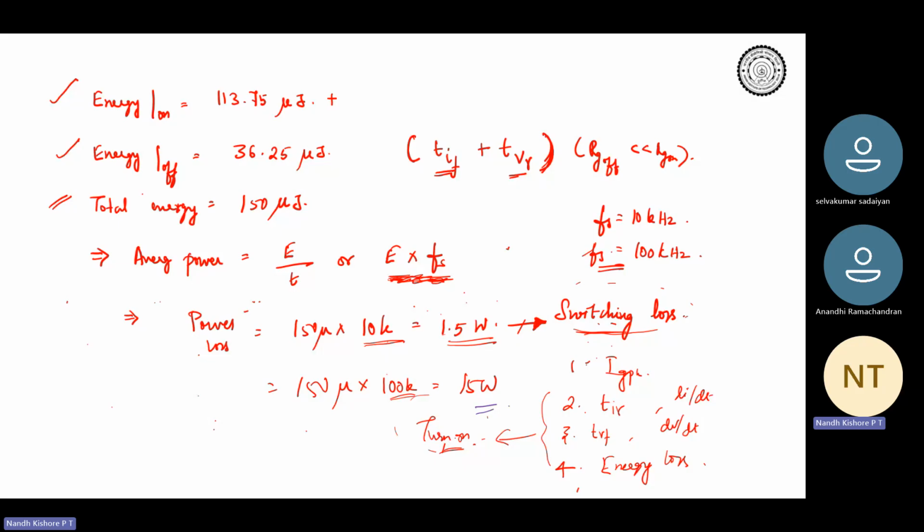Even in the buck converter, you would have seen the computation of how to calculate the value of L and C. You will see that it's inversely proportional to frequency. If frequency increases, your L and C value decreases. But on the other hand, if your frequency increases, the switching losses in the device will increase. Please don't forget this.